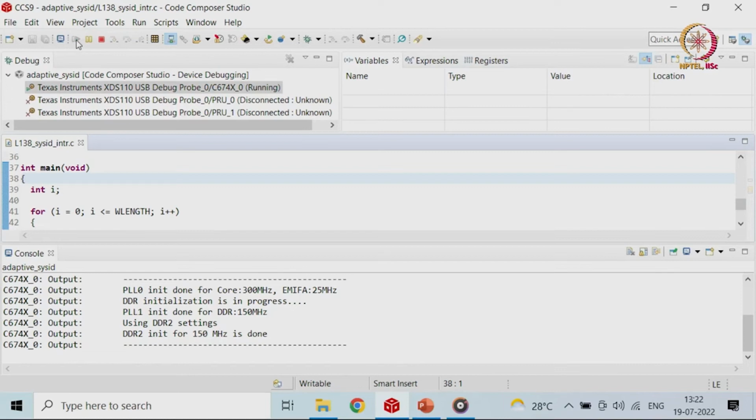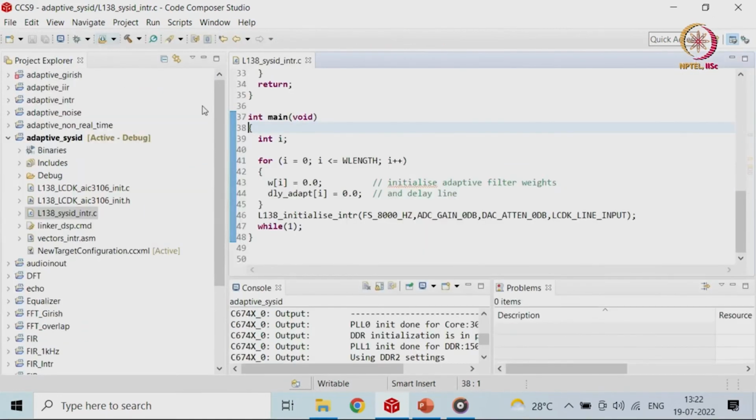As you can see, there is little error in whatever the FIR filter is adapting to, that is, the filter coefficients trying to remove this noise, and then I should be getting a clean sine wave, but still there is an error. So, this order may not be sufficient for it. You may have to go to a higher order to remove the noise. It is a little bit reduced, but it is still getting overlapped. So, you have to fine tune and then work on it.